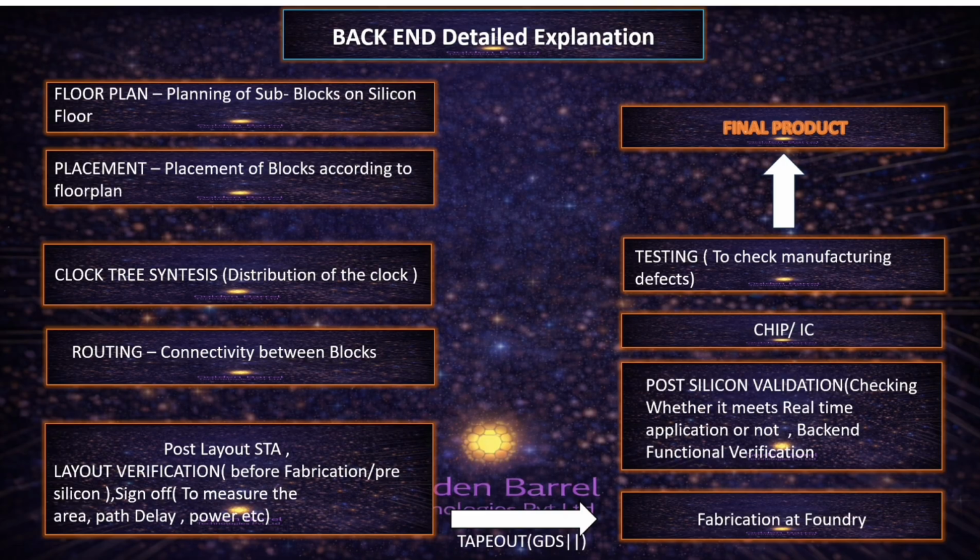Then coming to the post layout STA, or layout verification, sign off. I mentioned STA, static timing analysis. Generally in the front end, we are concentrating mostly on the functionality only, not on timing simulation or verification, but here we take care of it. And this is compulsory and more accurate than all other timing verifications.